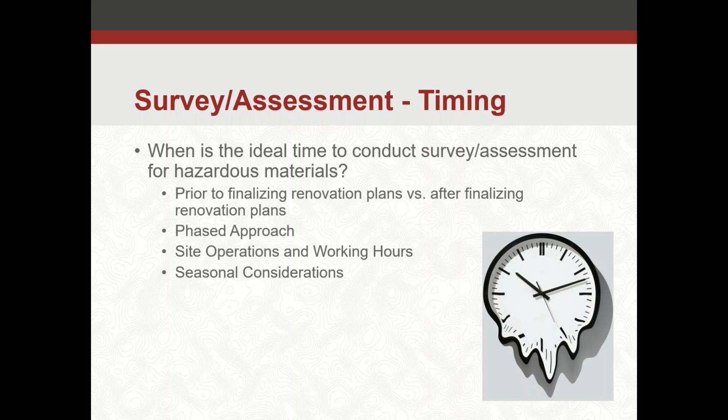We also want to look at site operations working hours. Again, do we have to work outside of normal business hours? And then seasonal considerations is another thing to pay close attention to. Subsurface investigations are obviously a little easier during your warmer months when you're not fighting snow or ice and things like that.